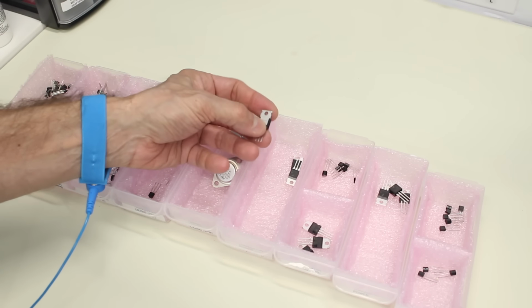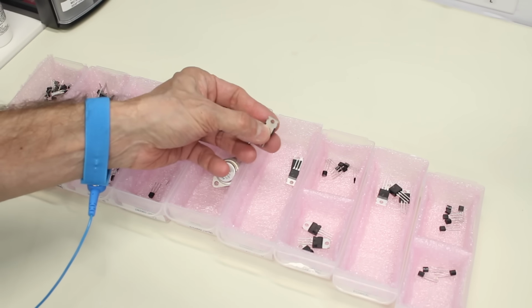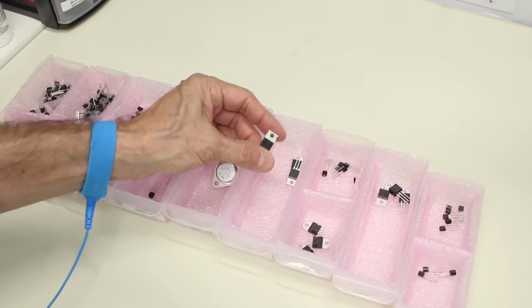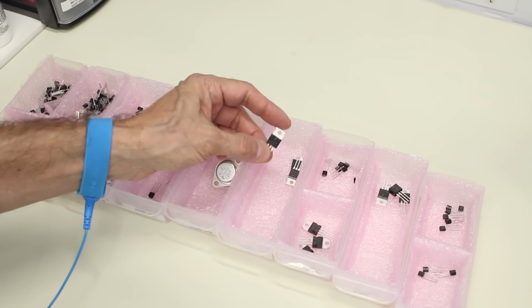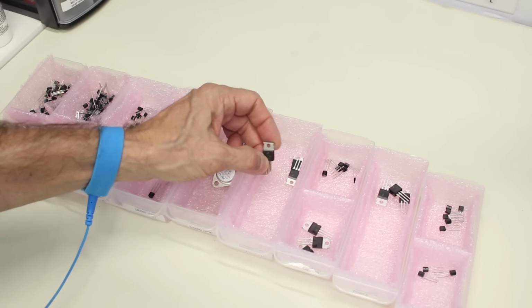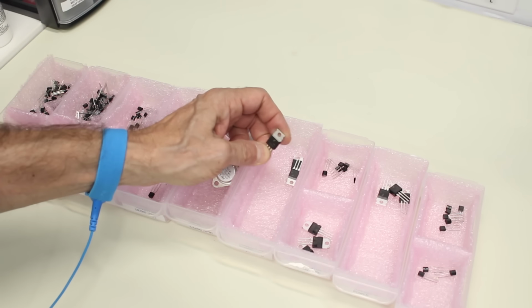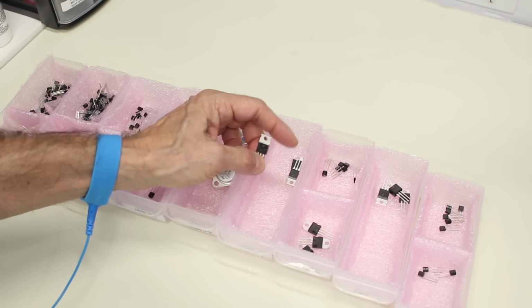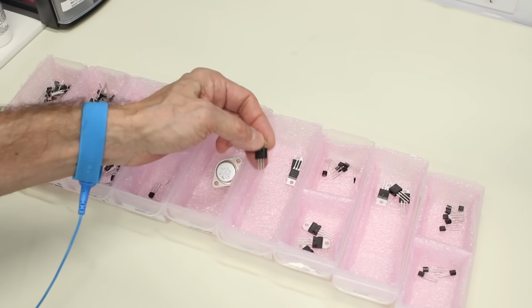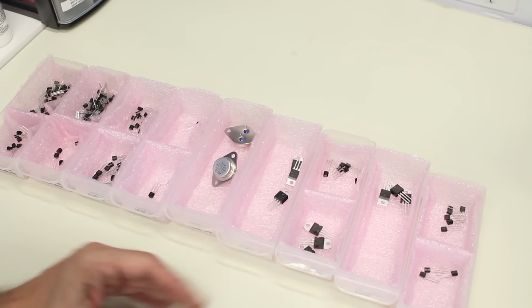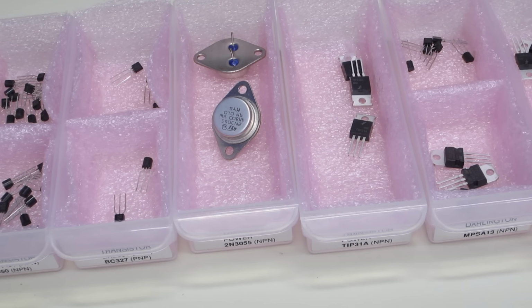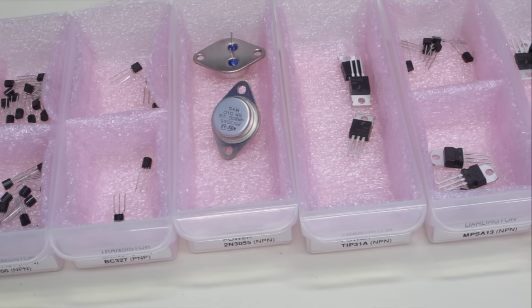Again, the heatsink side of the package will be connected to one of the leads of the transistor. So once again, when you mount this, you have to make certain to either isolate your heatsink from anything else or to use some form of an insulator. You have to be very careful if you're using a number of these transistors and you want to put them all onto the same heatsink. Again, you have to remember this is electrically connected to part of the transistors. But this is just an assortment for you of the different packages that you can get transistors and MOSFETs in.